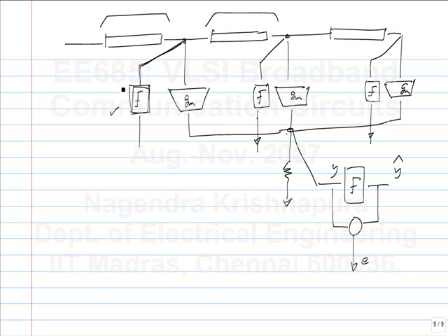Yeah, that's true. Again, the problem is a practical one. The transmission line already was very large. Now you are saying you will use a transmission line for the gradients also. That is a very suboptimal solution because you will use a very large area. First of all, this transmission line is a lumped approximation, so you use on-chip spiral inductors and capacitors to mimic a transmission line. If you have to do that for the gradient also, it will be a problem. And secondly, there will still be a mismatch between your two physically different transmission lines.